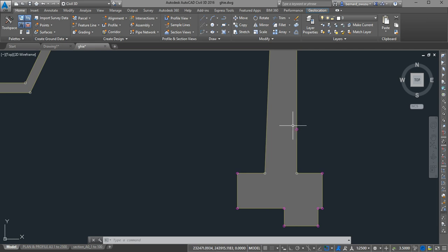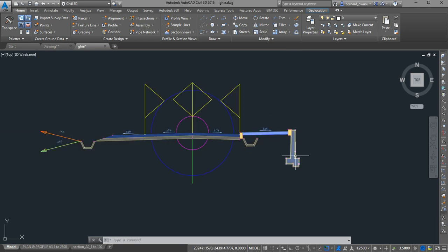or something. So depending on the cross section that you have, even at the toe here, you may have a toe drain. You may put a drain here. So you have to decide on what you want to do. Please, are you okay? So once you understand how to insert, you have your typical cross section. Then this will help you to draw a typical cross section. Then you apply. Please, are we okay?